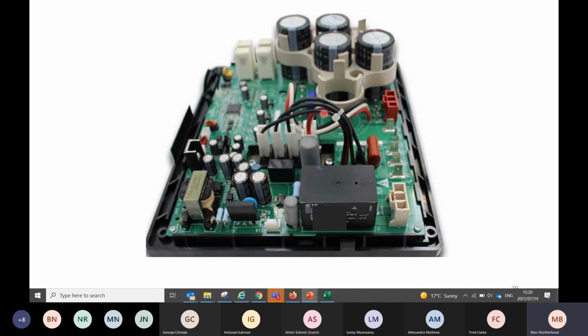It will allow the single phase to charge these capacitors, and this relay will then shut and provide a return path for the single phase. Once these are sitting at 320 volts, that little computer chip there will say, I'm happy. Open that relay. That neutral circuit becomes useless to man or beast.